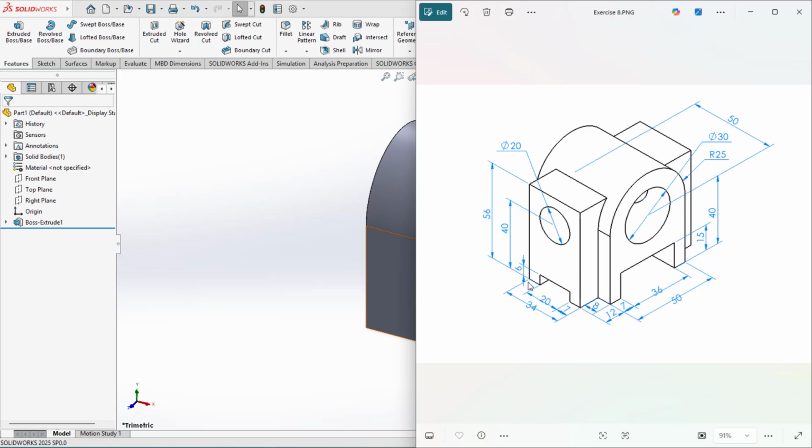Let's take a quick look at the drawing to understand the key dimensions for this extruded feature. Here you can see we created the base feature on the right plane and extruded it symmetrically, which makes the right plane the mid-plane of the base. So we'll start this feature on the right plane as well, since it serves as the mid-plane of the base. Here are the key dimensions.